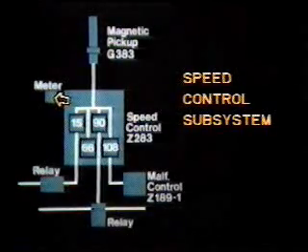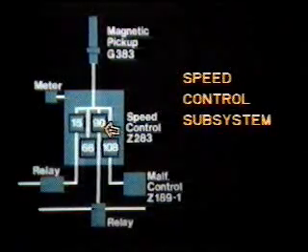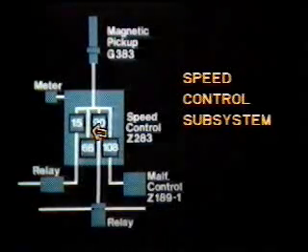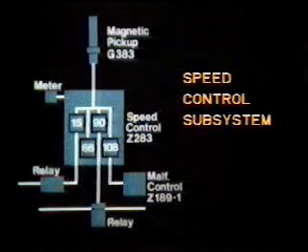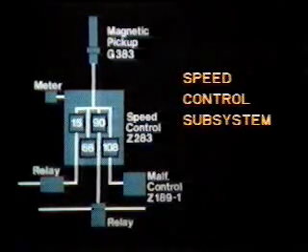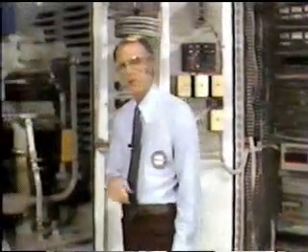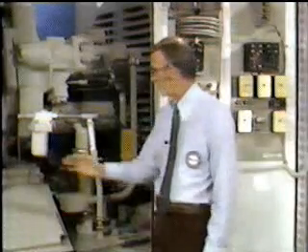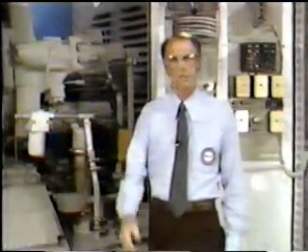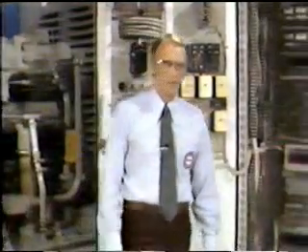The speed monitor has 4 gates which transfer at preset speeds. When a gate transfers, one or more relays are energized, causing other functions to take place in the engine. For example, the closed contacts of gate number 2 send signals to more relays. Some cause the starter system to deactivate, and others flash the field of the generator.